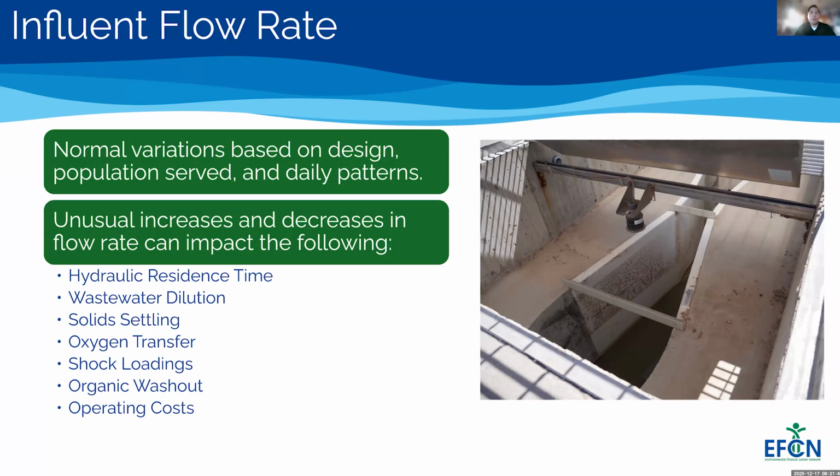But then again, if it has too long of a hydraulic residence time, that may mean that you are using more energy and are not optimized. So as with all processes in wastewater, you want to make sure that you have balance through all of those things.